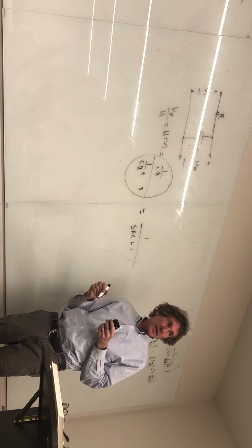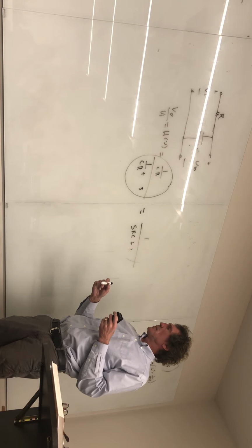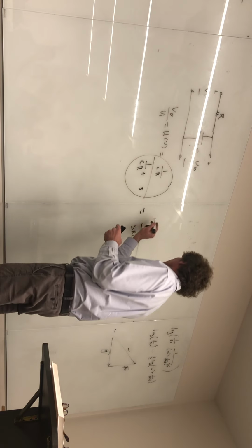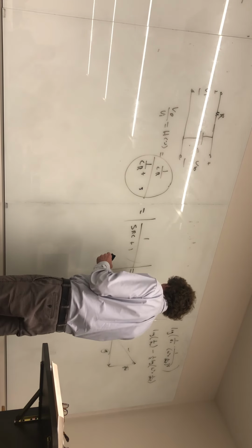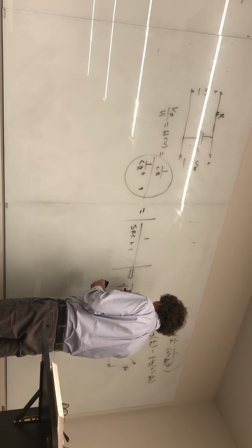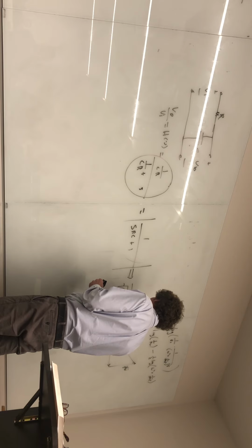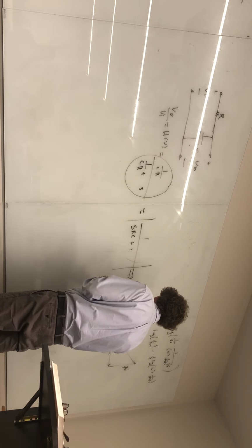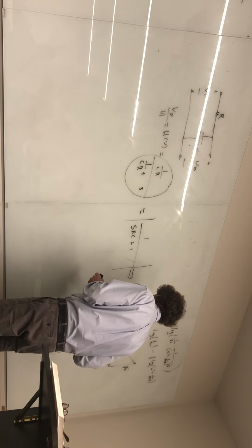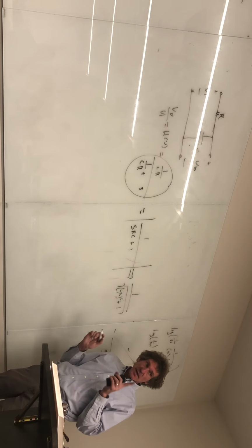Now they're going to put in the omega, j omega. Now you're going to get the magnitude of this, and just listen now. This will become 1 over the square root of (omega RC) squared plus 1. Okay? Now here's why they do that.